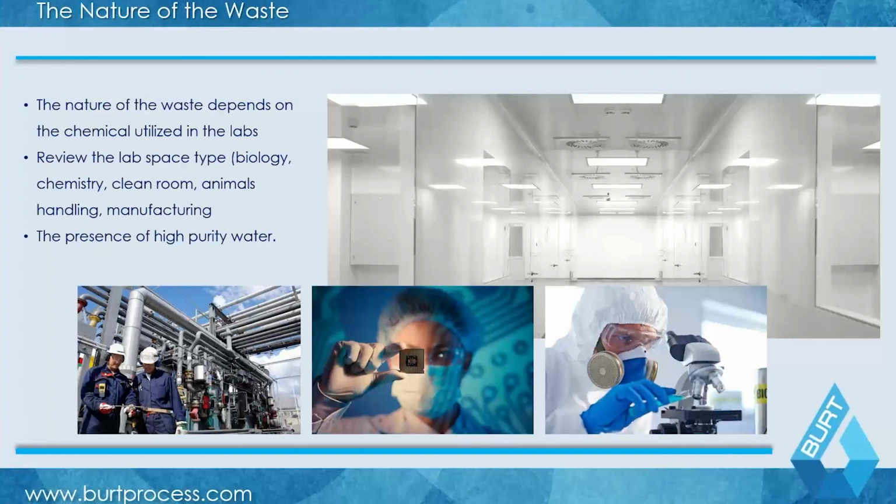There are a few things you want to look at. One, what type of space are we dealing with? Is it a biology facility, pharmaceutical, chemistry, clean room, animals, manufacturing, food and beverage? There are certain similarities in those, which can often point you to specific types of chemistries you'll see. For example, in pharmaceuticals and food and beverage, cleaning chemicals become very pertinent. Clean rooms or semiconductors, you're generally going to see things like aqua regia or other acid-based chemistries coming into your system. This can at least point you in the right direction as to what kind of waste you're going to see.